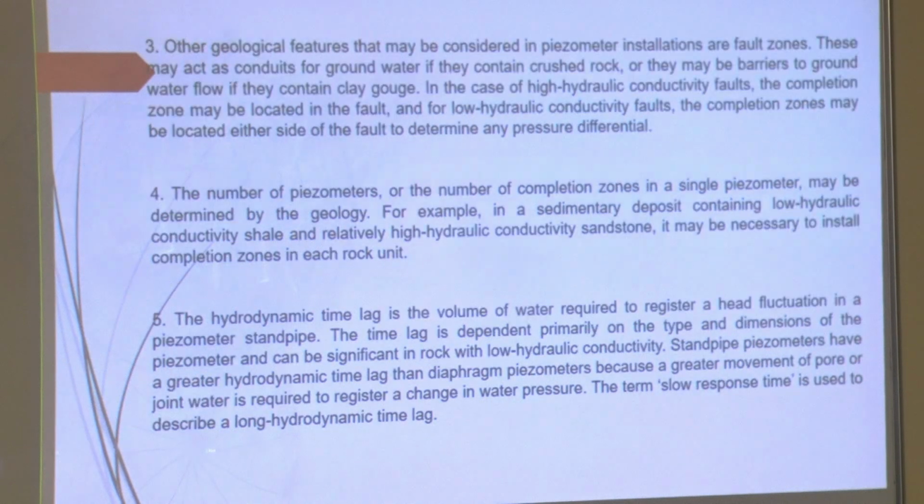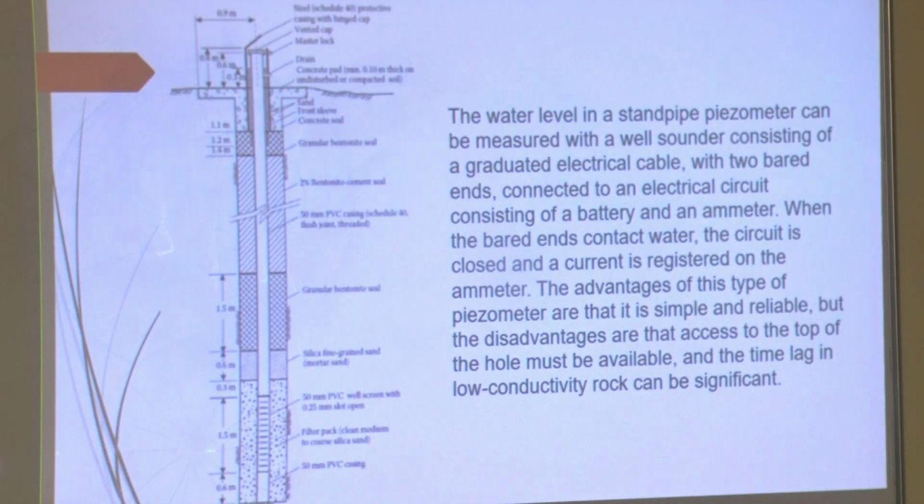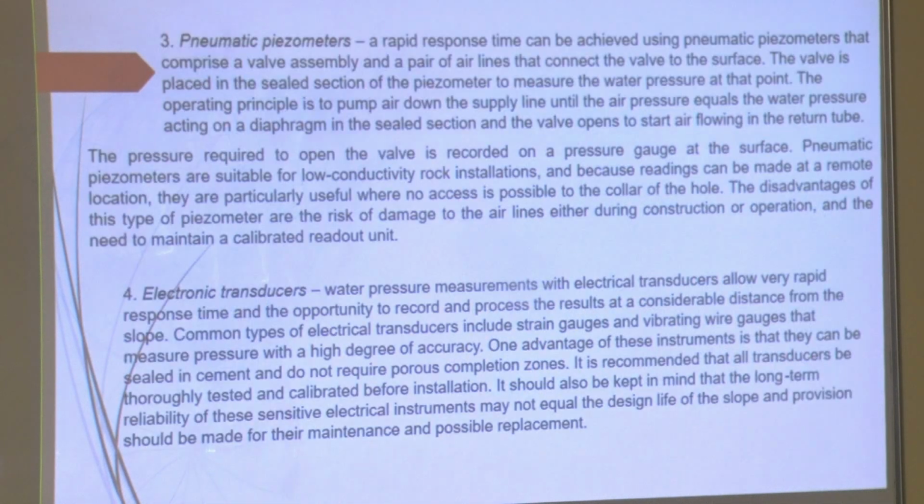And there are numerous methodologies to estimate and measure the amount of water flow in a rock joint, not in a rock joint, in a slope mass. So these are the possibilities. Generally, we use a standpipe. That standpipe can be fitted with different sensors, from vibrating wire sensors to pneumatic type sensors, that can analyze very precisely the amount of water developing, even a minute amount of difference.